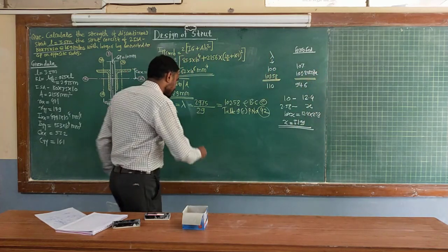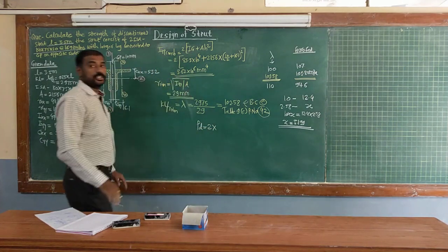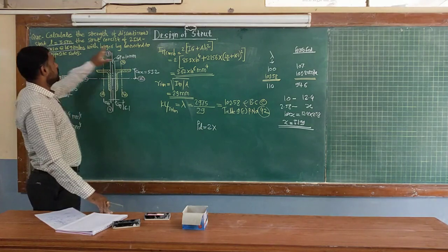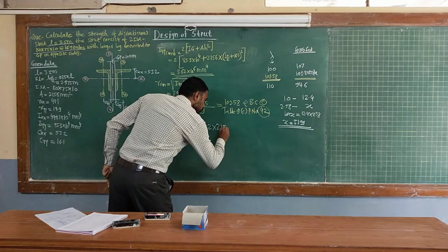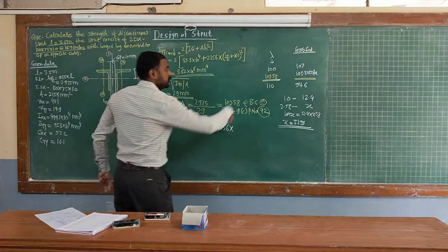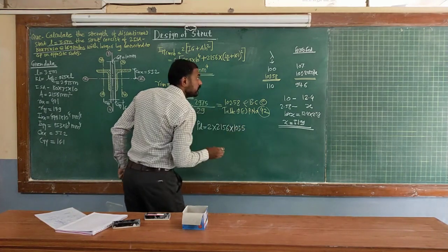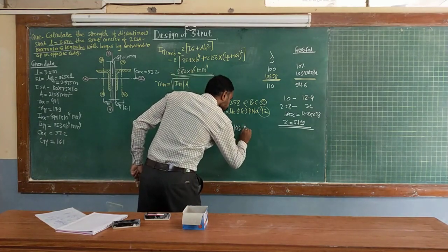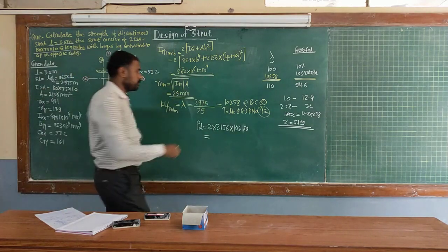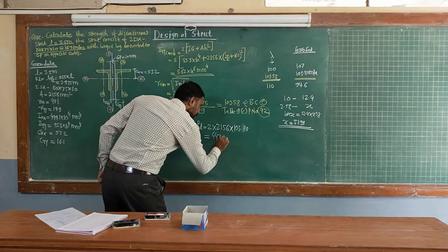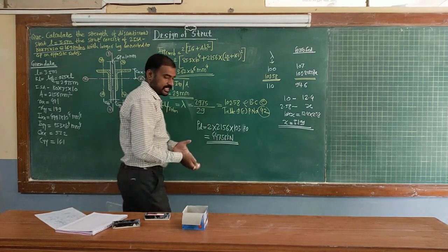So putting that value into the last step, design compressive stress PD is equal to 2 multiplied by, because 2 angle sections are mentioned, 2 ISA, and area of single is 2156, so 2156 into 2 multiplied by FCD, FCD value is 103.80, again divided by 1000, so the final answer is 447.58 kilonewton. Here the answer is completed.